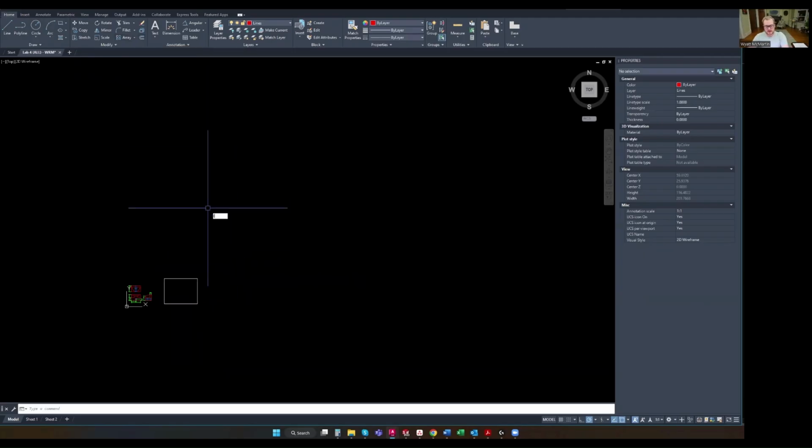So with that, L enter for line and kind of start somewhere. Let's start a little farther away, maybe somewhere like this. Drag it straight out to the right. And we are going to type the @ symbol and 33, tab, 90, enter. So what we're saying is that is going to be a 33-inch line at 90 degrees. That's distance and bearing. We haven't done that since the first week. Now above the 0 point here, type @20,17, enter. Then we're going to type 20, tab 0, enter.